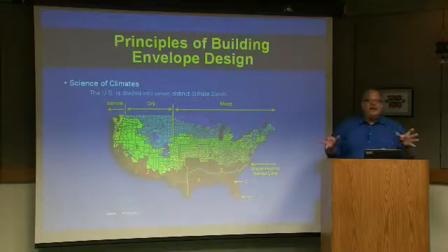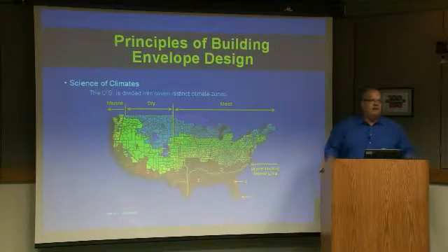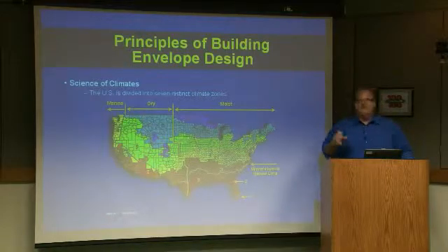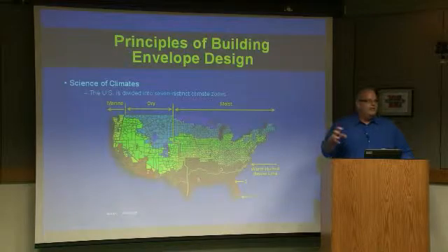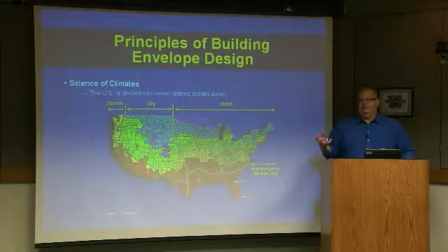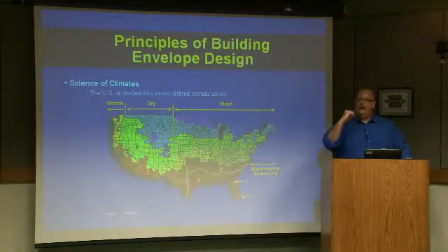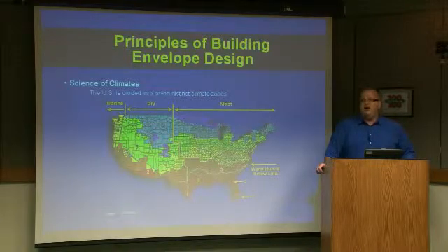You can have a house made out of EIFS, and you know woodpeckers love EIFS, and they'll go up and knock their head on it. It sounds like a rotten log, so they'll chunk out a big piece the size of a grapefruit. That can be left open in Denver, Colorado for 20 years. And you can check your probe and poke it into that OSB sheathing, and the sheathing is bone dry.